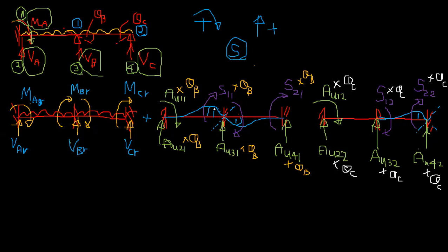Why? Usually these have been derived for unit rotations, in the appendix. Then I can apply what is the force or the bending moment for a unit rotation, unit displacement or a unit force, right? Then I can multiply it by the original displacement or the rotation, right?